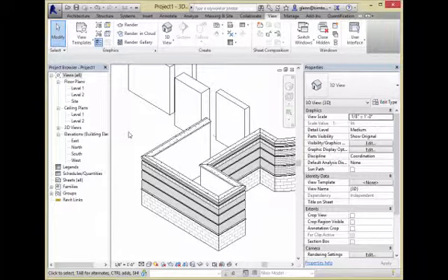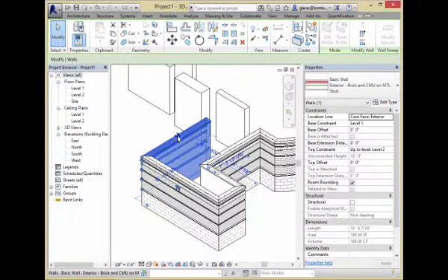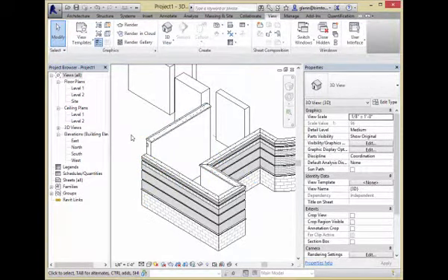Okay. So I've got all these walls, they're stretching around from level 1 to level 2 right now. And that's generally pretty cool. As you go through and create walls, you may want to have, in addition to openings, sometimes just walls at slightly different heights, offset to different heights, different bases. For any wall we can grab the wall and stretch it up if it wants to be a few feet higher, a few feet lower, whatever it is. We can grab it by its top, we can grab it by its bottom. This notion of changing the tops or bottoms, we tend to describe as offsetting from the top and bottom. So let's talk about the wall and how it's defined.